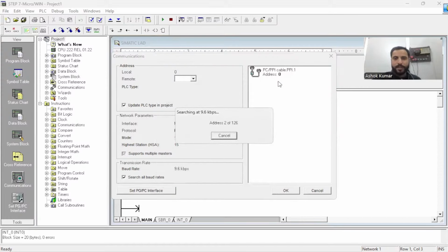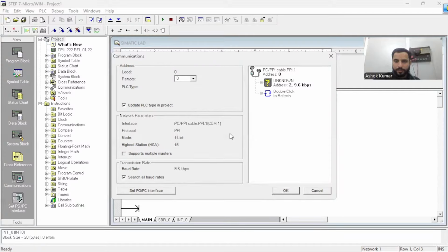It will start communicating, and once it starts, you can see the driver. Although it is communicated, let it complete first. Don't cancel in between. Don't interrupt the process. This is the way to communicate. Now we'll make a start stop logic, then we'll jump to timers.